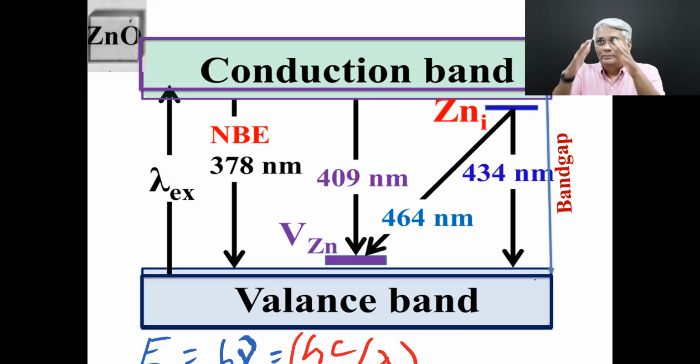So luminescence is subdivided into two parts. You have fluorescence and phosphorescence. Fluorescence happens as long as the excitation source is on, right? The source is on, and this process of carriers going to the upper levels and making transition back, recombination leading to light emission, is happening. Phosphorescence is when, even after the source is cut off, you still see some emission happening because of detrapping of carriers from higher levels back to the lower energy states because of the existing thermal energy, say room temperature.